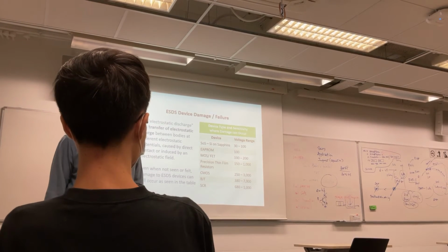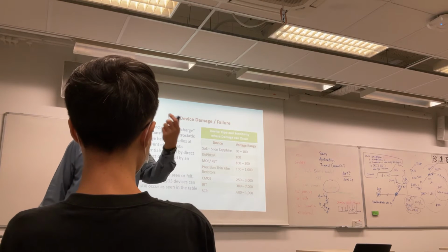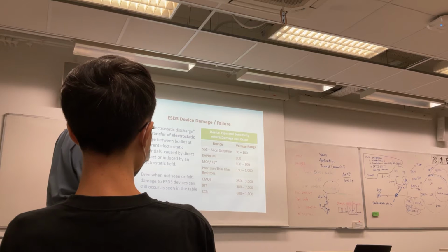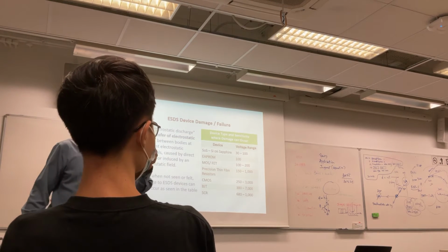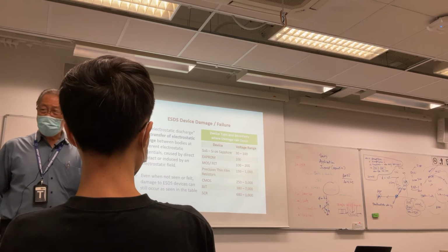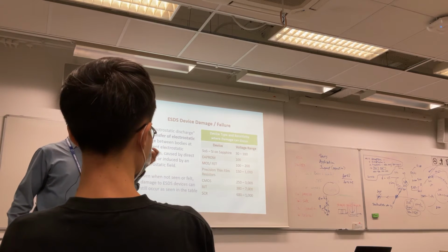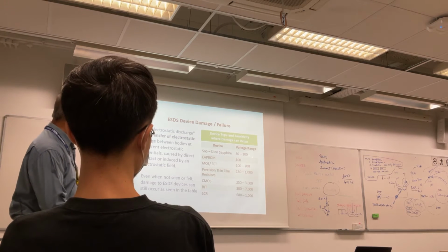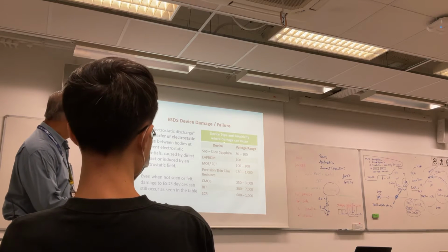And what is this? Thumb drive. Your thumb drive is an EEPROM. And this is very susceptible, don't forget that. Why? Because the thumb drive is very efficient, you use very little current. Because you're using low voltage and low current, it becomes more susceptible to damage. Of course, this is even worse. So this is the range of things that are sensitive.